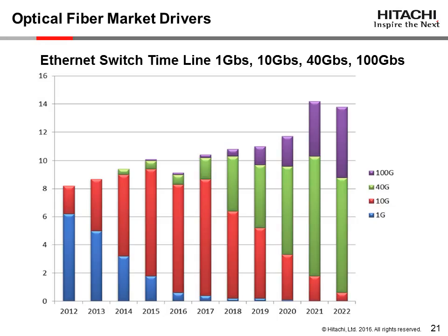1 gigabit per second applications are in blue, 10 gigabit per second applications are in red, 40 gigabit per second applications are in green, 100 gigabit per second applications are in purple. It is expected that older 100 megabits per second systems will begin to be obsoleted and upgraded to 1 gigabit per second and 10 gigabit per second systems over the next several years, most likely using OM3 and OM4 fibers. 40 gigabit per second and 100 gigabit per second applications will begin to focus on use of OS2 fibers.